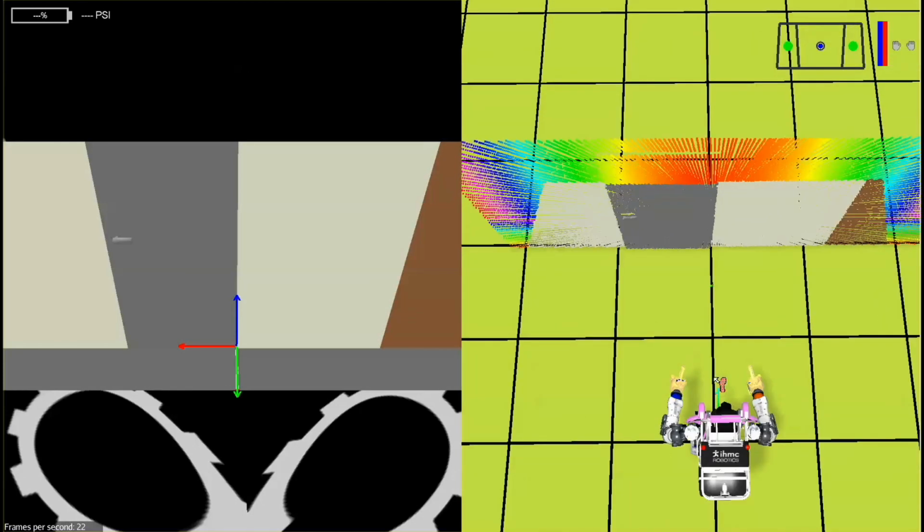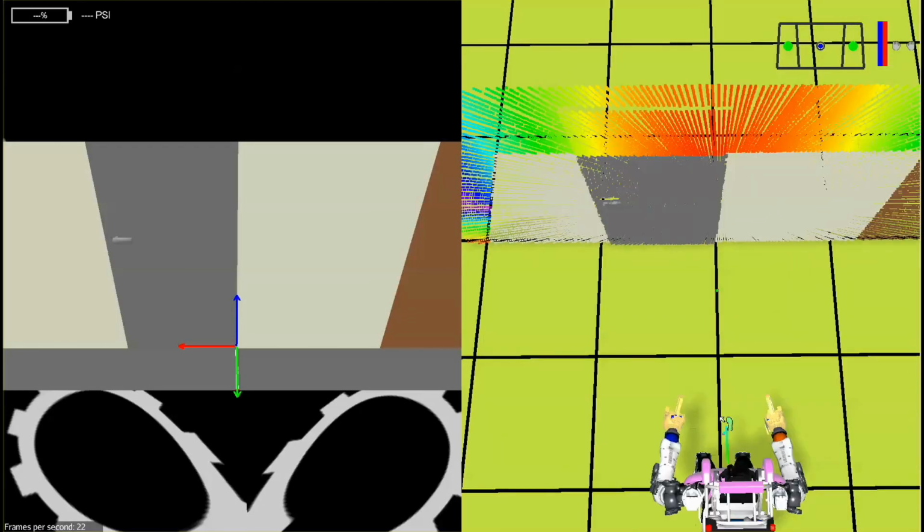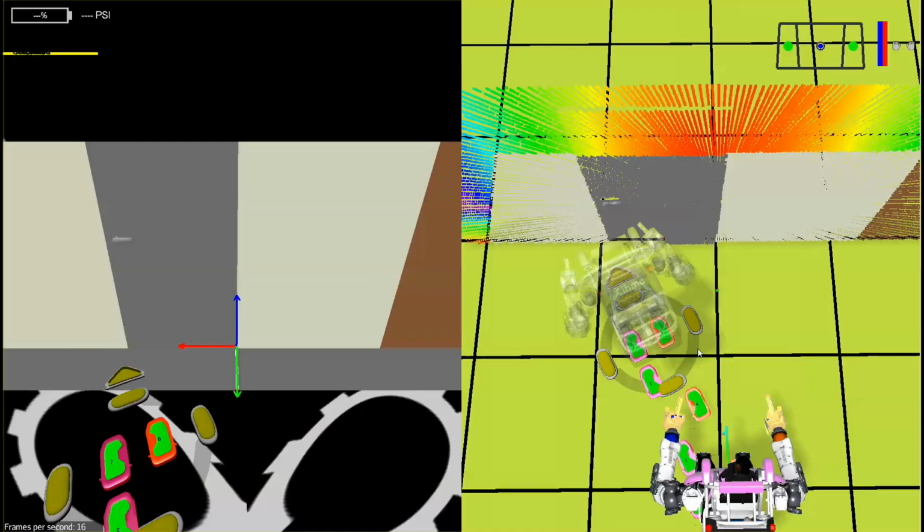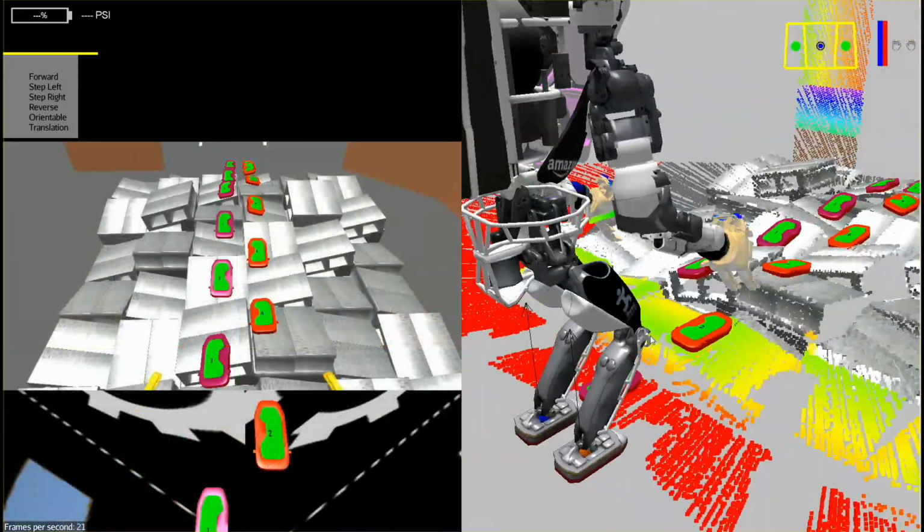Here are several different ways the human and the robot can interact on footstep planning. The human may want to manually place individual footsteps, but it's more likely they'll rely on automated planning algorithms. However, the human may want to tweak those automated solutions, for example by adjusting the end stance, or maybe shifting individual footsteps within a plan that seem to be too risky.